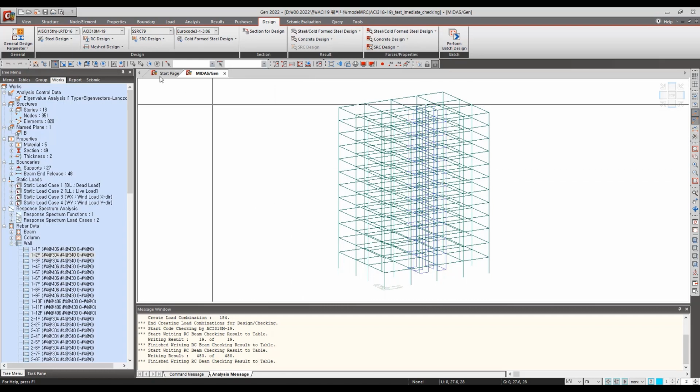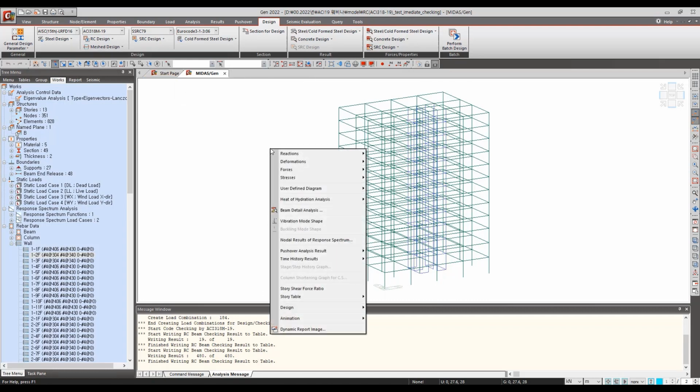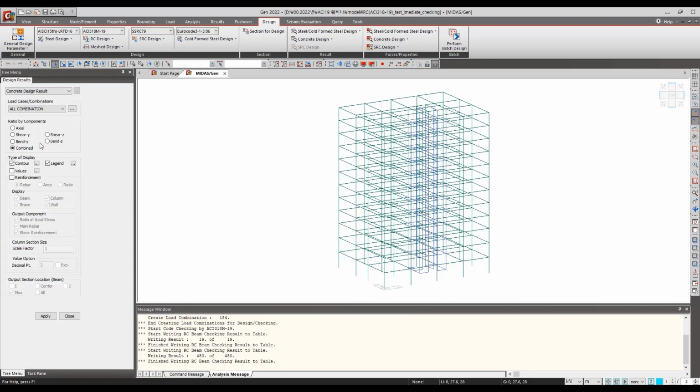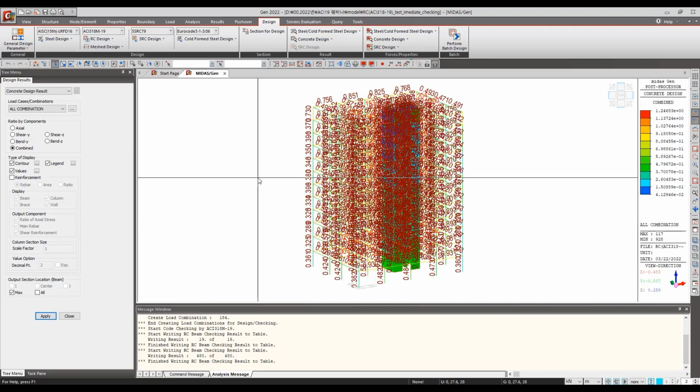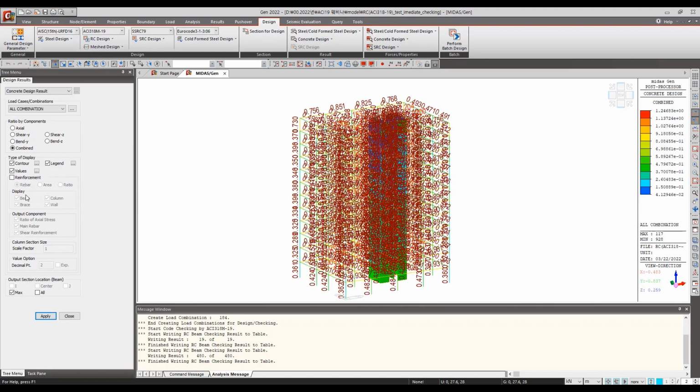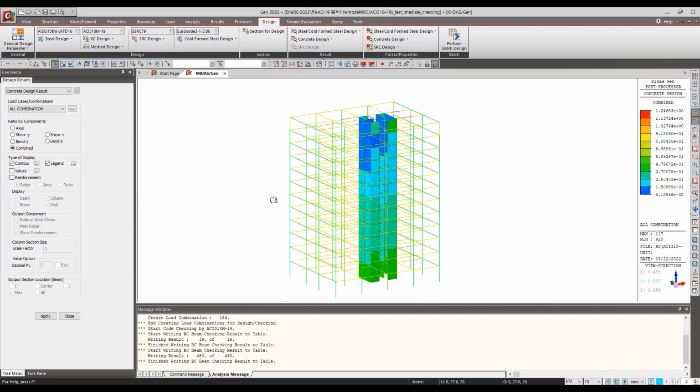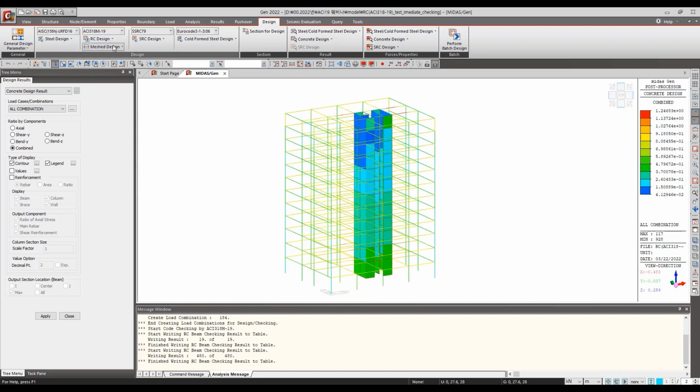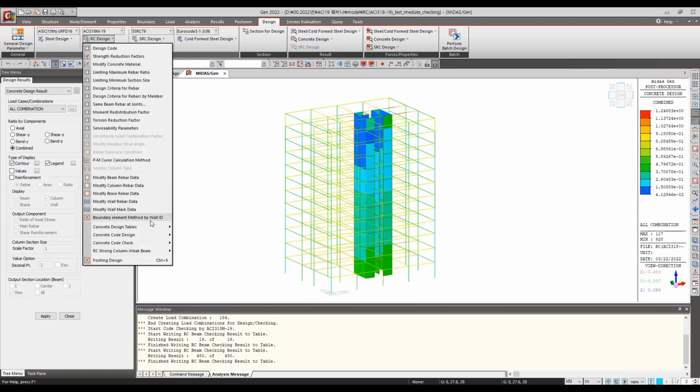We explained that the change in shear capacity calculation is related to the amount of flexural reinforcement, rho w, and also to the size effect factor, lambda s. This is obviously not the case in all cases, but in this case, we can determine that the 19 standard requires a greater amount of shear reinforcement or flexural reinforcement than the earlier ACI 318-14.